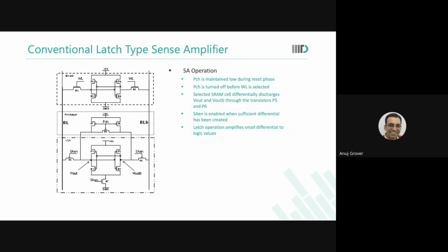But on silicon, if you do not draw things common centroid, you could observe some extra offset requirements in different parts of the wafer. Now, if you do not have timing margins in your design, then that could lead to failures, yield loss. You don't want that. So what you say is that, okay, if I have a device, let us say I have two devices, A and B. If I design them just like one finger, then A ka center of gravity is here, B ka center of gravity is here.